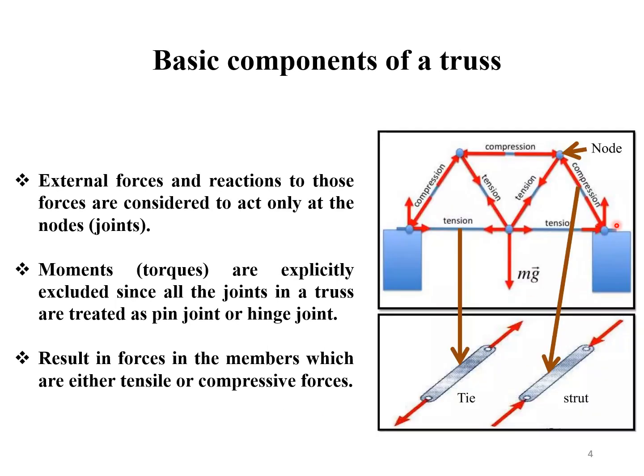There are two important assumptions we need to be able to make for a structure to be considered a truss. First, we need to be able to assume that all of the joints in the structure can be taken as a pin connection. Look at the first picture, meaning that members are free to rotate at the joints. The second assumption is that the loads are only ever applied at the joints of the truss. We never have loads acting in the middle of a member.